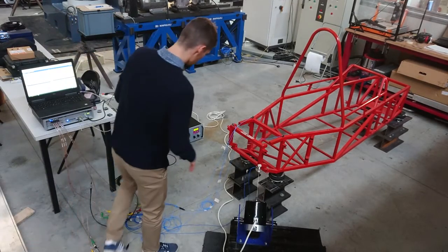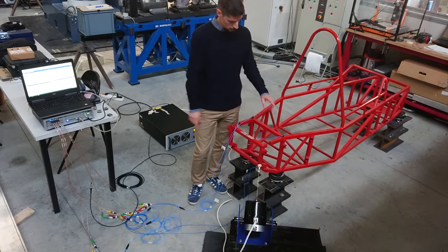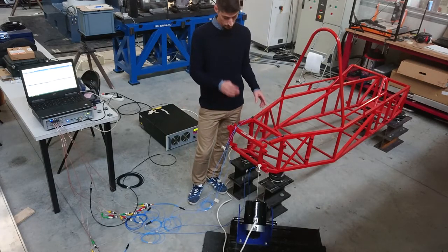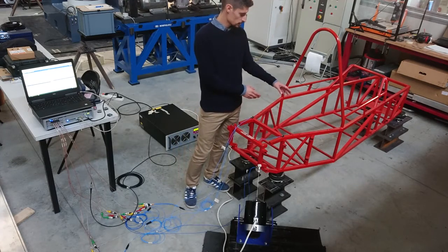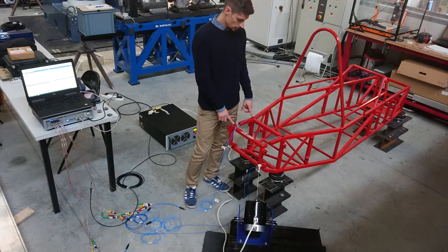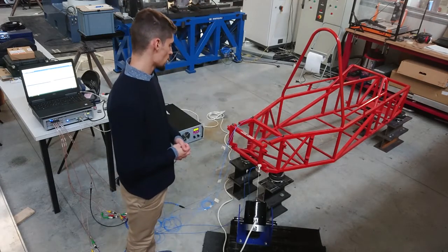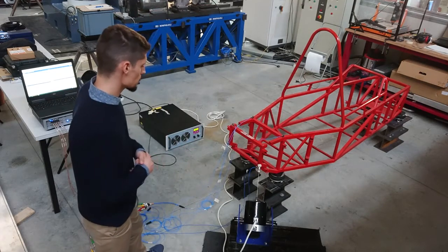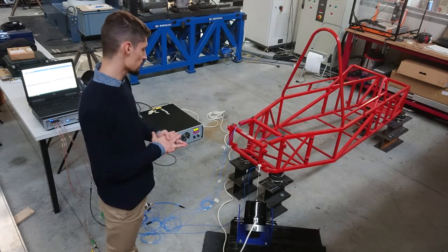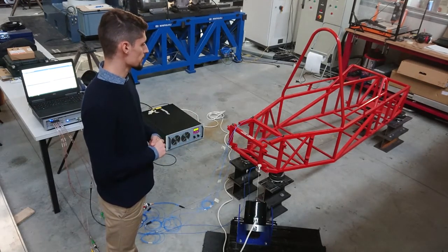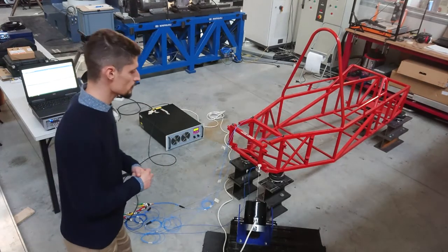Therefore, for performing this analysis, we will use just 4 3-axial accelerometers, and we're going to attach the accelerometers to the first 4 points and perform the first run. Then we will move the accelerometers to other 4 points and perform another run, until we have measured all the 21 points. So 6 runs in total. At the end, when all the runs are done, we will collect all the runs in one single file for estimating the FRF. So that's all about the introduction, about the test equipment, the sensors, and so on.